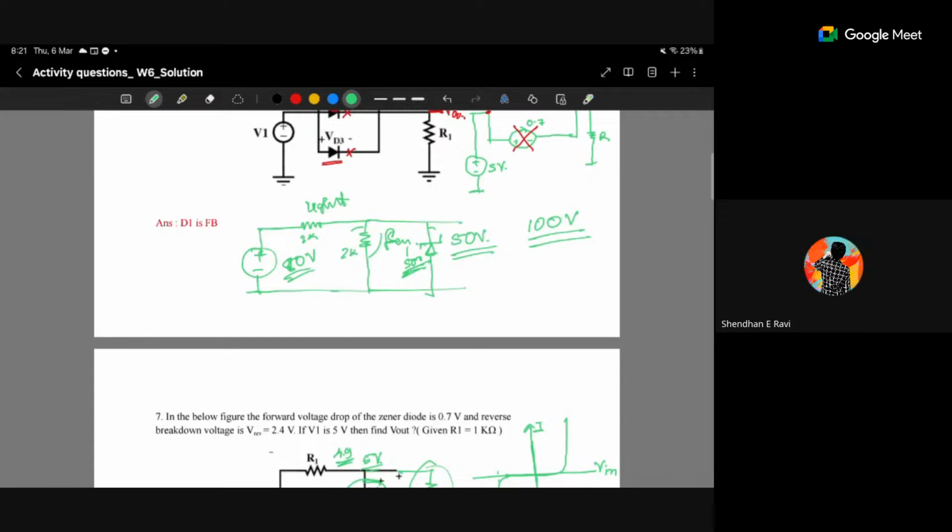Right? Yes, sir. So if you are buying a Zener diode to create a circuit, you first have to think about the situation and whether we need the Zener diode or not. In forward bias a Zener diode is as good as a normal diode, so why buy a fancy diode?